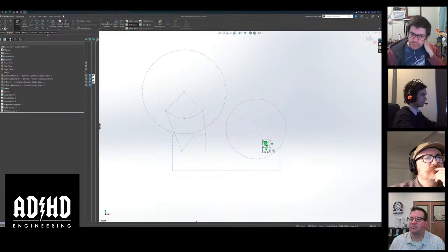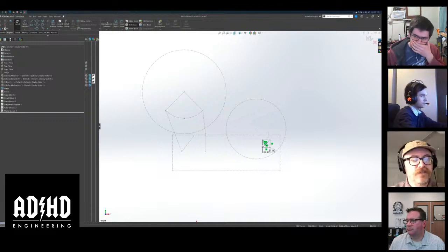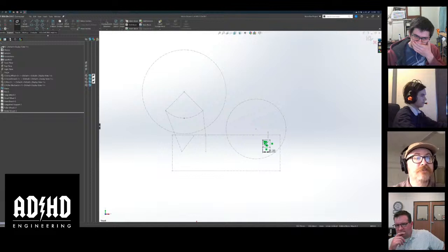The layout sketch has the, what do you call it? The insertion point defined. So then if you fix that, it shouldn't be movable, right? I don't really understand why it would be moving. Well, no. Because that anchor point, the fix position, it relates solely, and I mean really, to nothing else other than itself. So if you notice, there's no origin in this sketch right now.